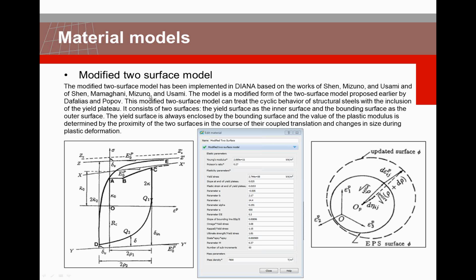and colleagues. And this is a so-called plasticity model with two yield surfaces, in which the hardening of the concrete is dependent on the distance of the stress point from both yield surfaces. And this is a model that is pretty advanced for cyclic behavior of steel. It's available for all types of models, varying from reinforcement bars or truss elements to full three-dimensional models or curved shell elements.